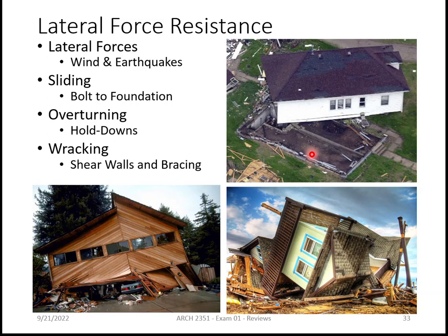We may use more bolts, bigger bolts, or whatever, but we always bolt the platform, the floor platform, to the foundation, or the wall to the slab on grade. Hold downs, you don't see that used a whole lot except in very extreme condition places like earthquakes, like in California, where they have a lot of earthquake conditions.